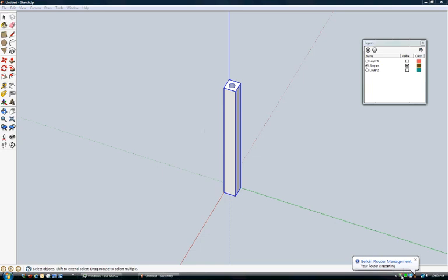Now what I'm going to do is choose my select tool, and I am going to highlight everything within that drawing. This is where I use that group function that I mentioned earlier. I choose edit, and I go down and I make this a group. Do not make it a component. That gets into more advanced modeling. At this point would probably mess you up.